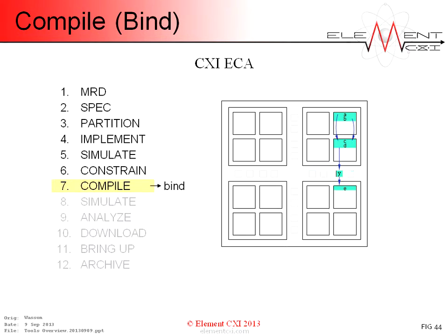ECA mapping and placement are greatly simplified because every element in every zone has unit delay connectivity, so it doesn't matter where a context is placed. All connections being unit delay preserves performance, and this greatly simplifies simulation and timing analysis.